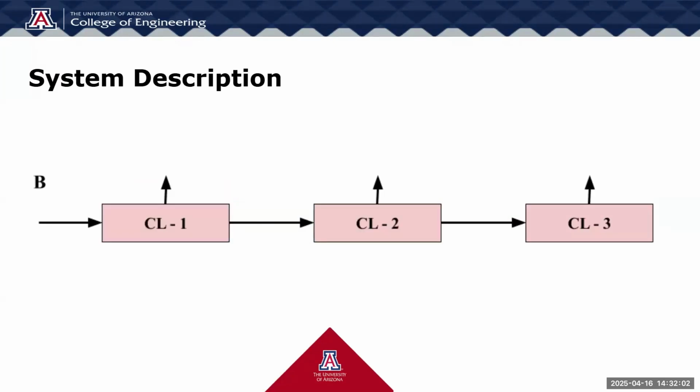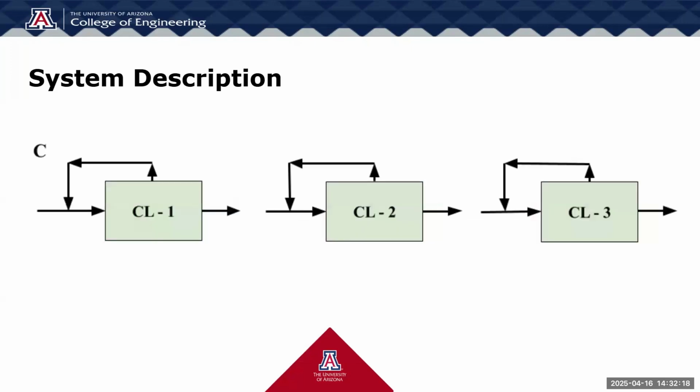In Exhibit B, the outlet air from Cleanroom 1 is sent to Cleanroom 2, and the outlet from Cleanroom 2 is sent to Cleanroom 3. Each cleanroom transfers only the necessary amount of air to the next, and any excess air is exhausted. This approach reuses some of the conditioned air, helping to reduce energy usage.